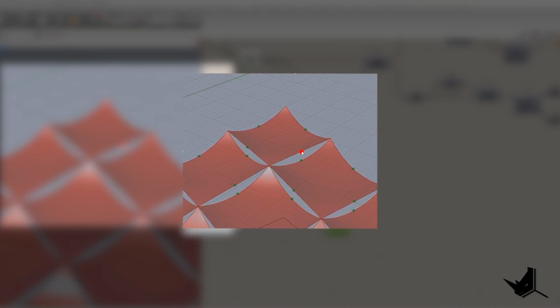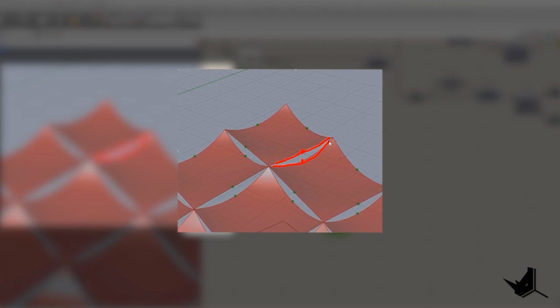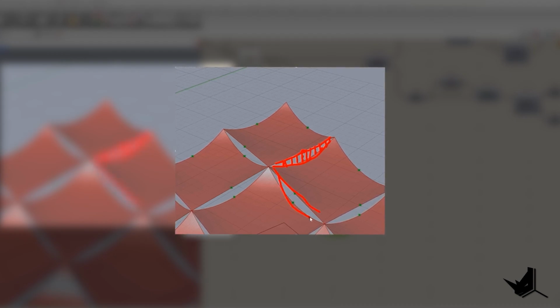Obviously, the first point will be overlapped point, but the next one, the next closest one, will be this guy here. We can extract index numbers of these 2 points and also these 2 curves and place them in the same branch. Once they're placed in the same branch, we can use a loft to create the surface. And this will be used for all pairs of segments.